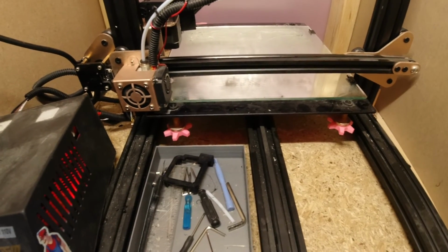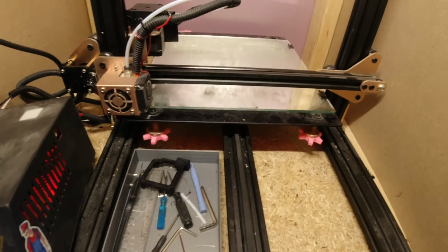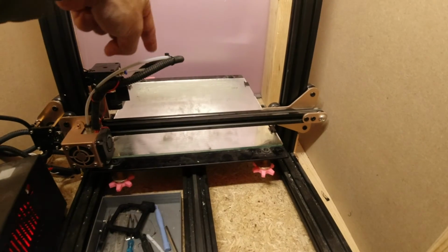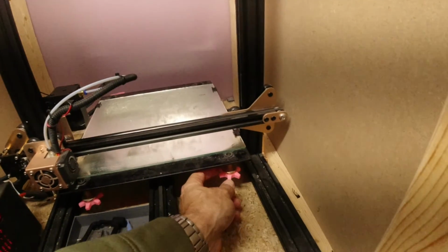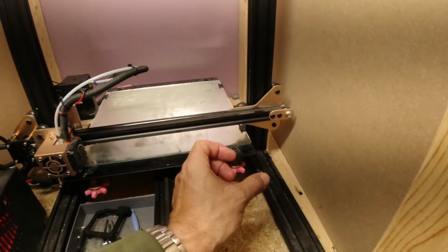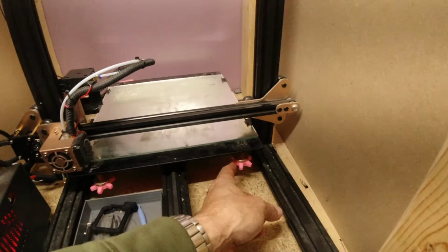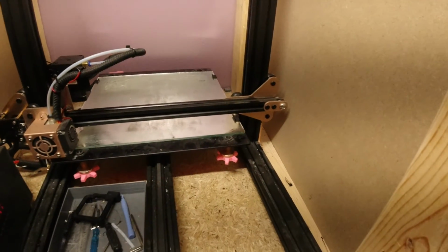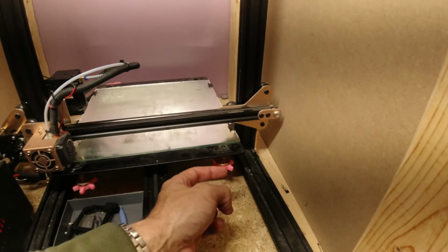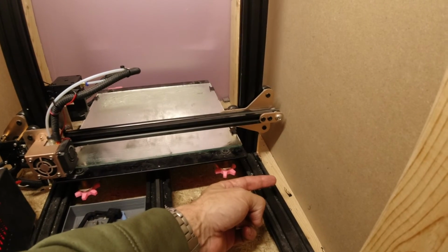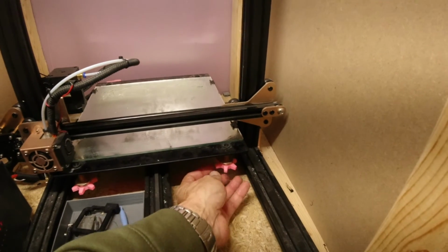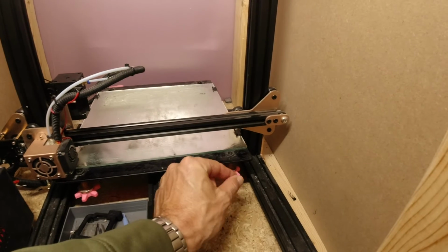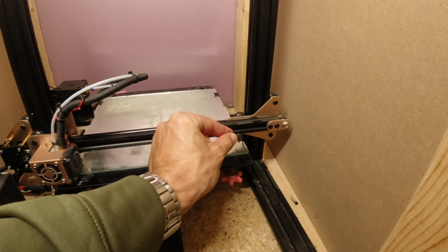Alright, it is heating up and getting ready to print. So what's going to happen is it's going to put our square down on my mirror here, and then we can adjust these knobs to fine-tune that bed level. You want to go basically the opposite direction because you're looking at it from the top down. So turning it this way, is that right? Yeah, this way will tighten, this way will loosen. So when it tightens it, it brings it lower, and when you loosen it, it lets it raise up.